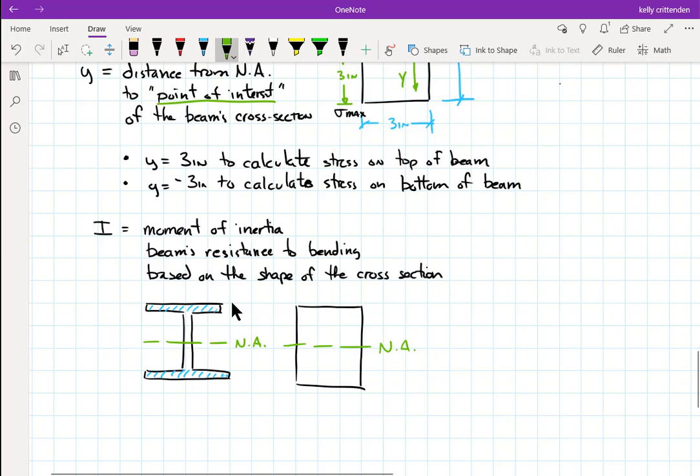I mean, an I-beam converted over to a rectangle would just be this massive beam. And you could get almost the same performance out of the I-beam, which doesn't have all of this material in here. All of that's missing, but it has almost the same performance as that solid piece of rectangular steel or whatever it is you made the thing out of.